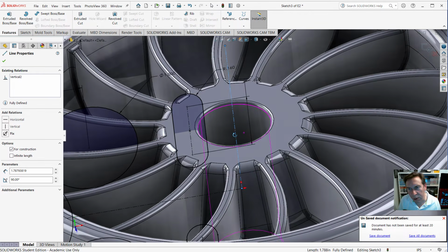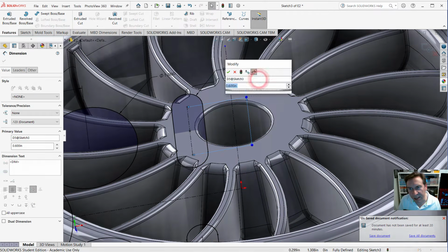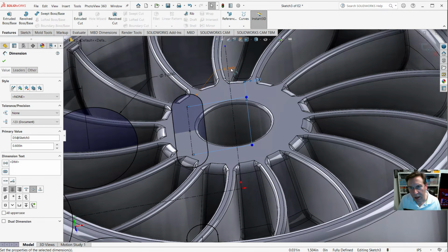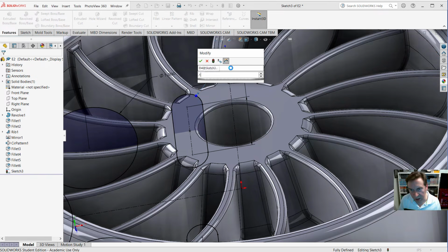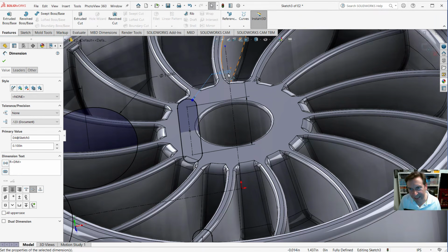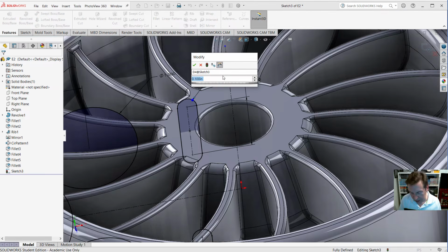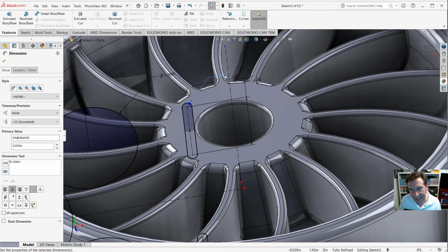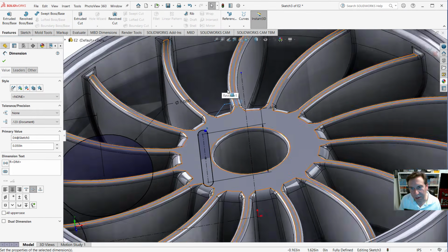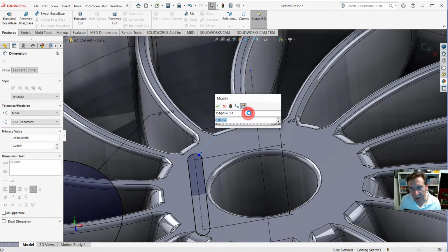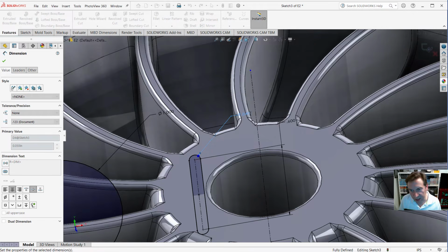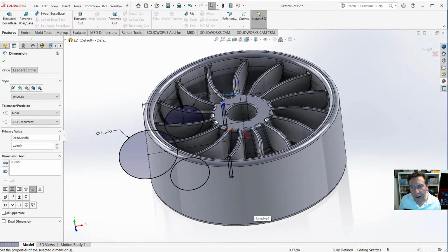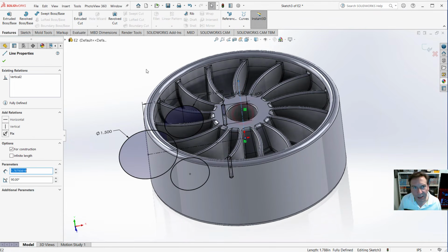Yeah, that's too deep. Let's see here. Double click on this. Let's make it... Oh, not that one. Sorry. Double click on this. Make it 0.1. Let's see if that makes it smaller. Nah, it's still not what I like. 0.05. Anyhow, we'll probably go even lower than that. 0.04, so it doesn't touch the edge. There we go. And you'll see how to make a cutout slot. That's cool. All right. Now select this center line.